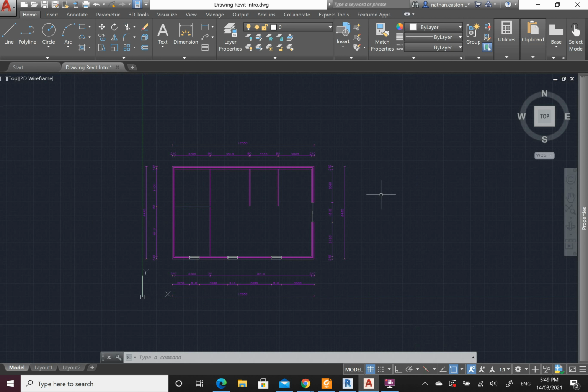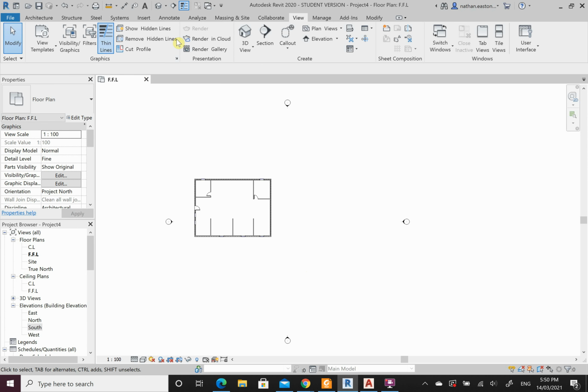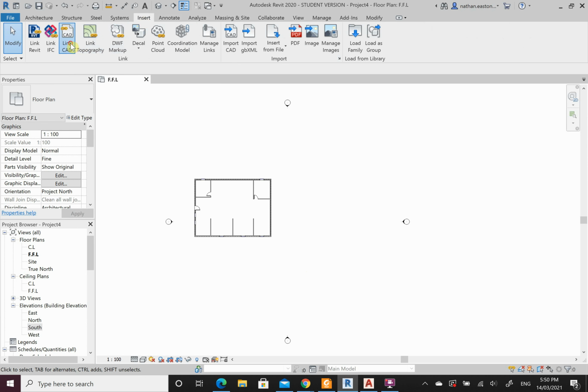This is going to save you a lot of time messing around with Revit, because what will happen is you'll import it into Revit, you have a lot of other things in your drawing, and it's going to end up being 33 kilometers away from the origin. So do this, it's going to save you a lot of time. So save it. Alright, this is what I'm going to bring in. I'm going to bring in this CAD file. Back into Revit, insert, link CAD.